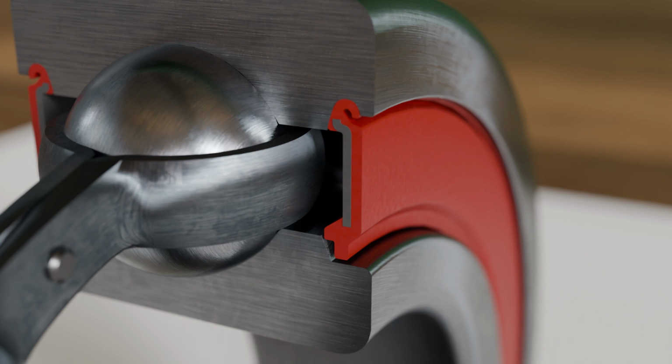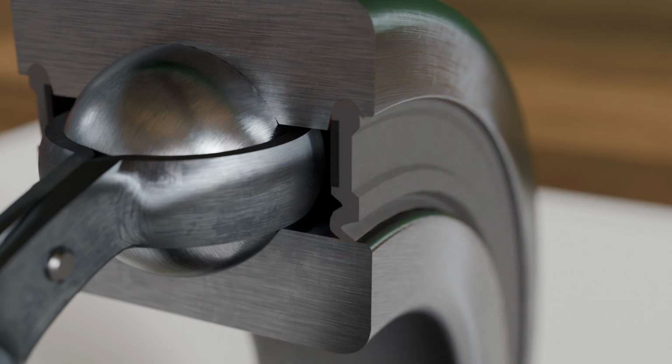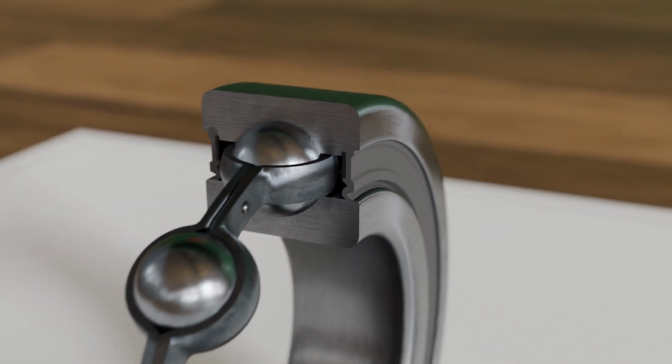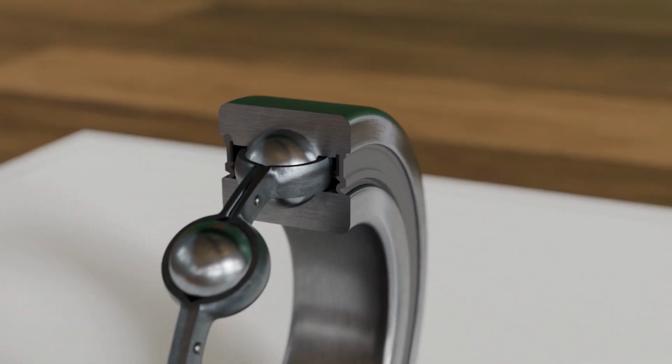An even higher sealing effect is achieved by seals with a sealing lip that directly contacts the inner ring. These contact seals provide near-complete protection of the bearing interior but generate additional friction. As a result, the maximum rotational speeds are significantly lower than with non-contact seals. In the shown designs, the rolling elements are arranged in a single row only. This is why they are also called single-row ball bearings.